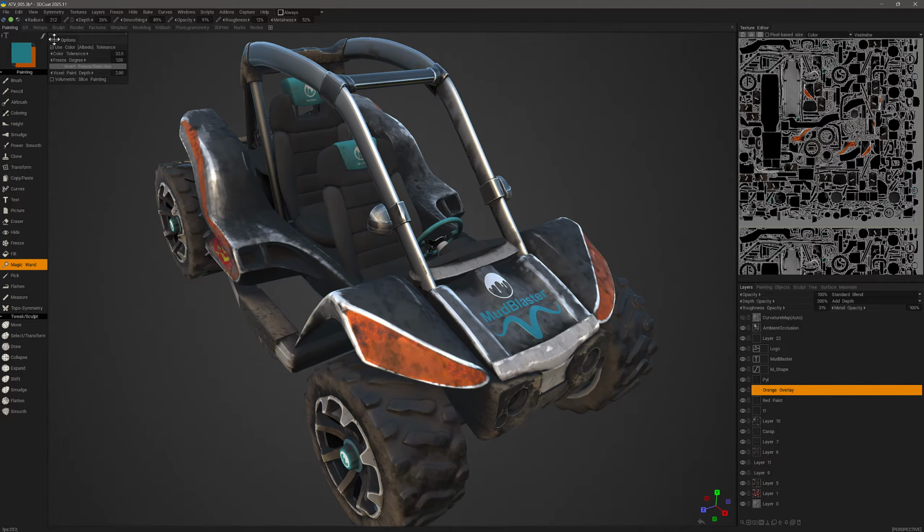So in the Tool Options panel, we have the ability to use color tolerance, which has the same value by default as Photoshop, but we could change that if needed. We could also adjust the freeze degree so that we let some degree of opacity through when we're painting or some depth when we are sculpting. But we will stick with the default value of 1, which is essentially 100% for this demonstration.